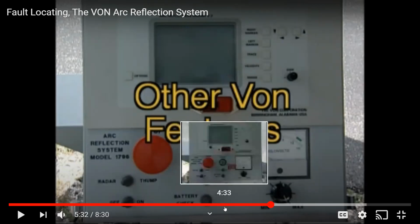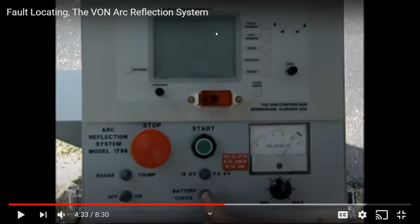There you go. If I'm working with 7,200 volts on my normal operating system, how many volts? It's a 15 kV cable, so it will go to 15,000 volts. Sometimes you're going to have to pump that voltage up a little bit, especially if you're in dry sand conditions, but you never really want to go over 10,000 volts. So if you got a 15,000 volt cable, 10,000 volts is plenty. If you got a 34.5 kV cable, I wouldn't go over 20,000 volts on it. All right, if it hasn't faulted out by that time, you may still have a good cable.